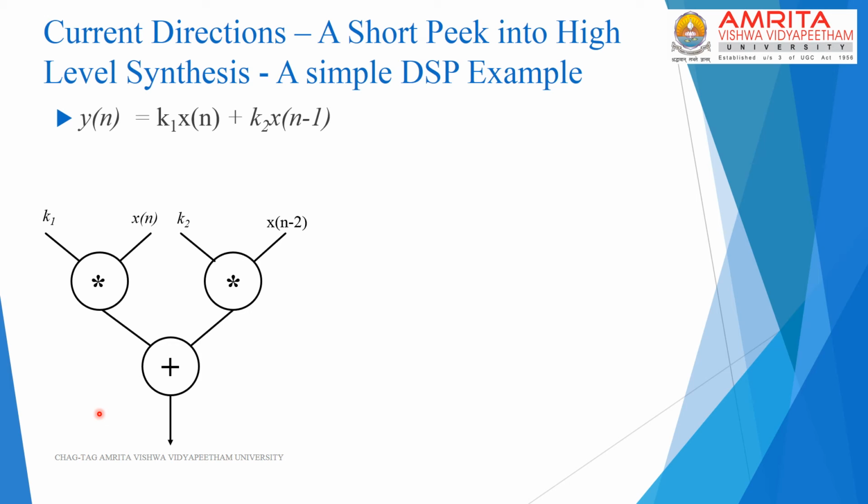But typically most of these design flows are constrained by the number of resources available. So in this case, there may be a constraint that you can use only one multiplier, because we all know that multipliers generally take up a lot of area, especially the parallel multipliers.